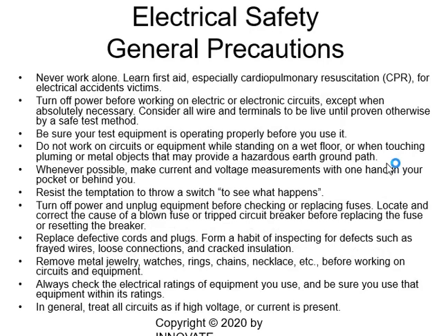General precautions for electrical safety. Never work alone. Learn first aid, especially CPR or cardiopulmonary resuscitation for electrical accident victims. Learning CPR is extremely useful in any case, but especially when you work in an electrical environment. Turn off power before working on electric and electronic circuits, except when absolutely necessary. Consider all wire and terminals to be live until proven otherwise by a safe test method.